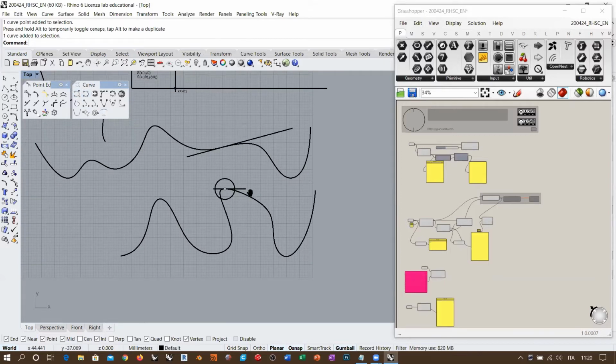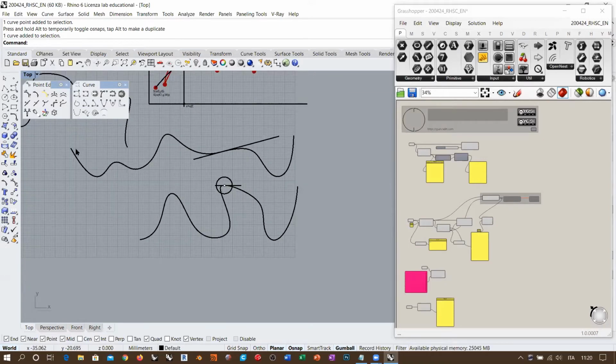So knowing this, we already know how to work with a NURBS curve which has a specific direction at the start and end, and also that can pass through a specific point. Actually, we can reproduce the behavior of an interpolated points curve using just these two simple rules. And we can be more precise, because we cannot, for example, use an interpolated points curve in order to define the initial direction.